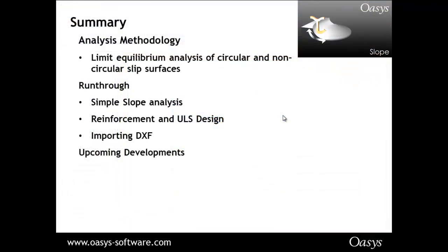So in summary, I've run through the analysis methodology. So now you should understand a little bit more about the limit equilibrium analysis of circular and non-circular slip surfaces. I've run through a simple slope analysis. I've also helped you look at how, for example, you would approach factor design in Slope, and then go on to design reinforcement. We've looked at, for example, putting raised groundwater tables in, putting loading on the slope. I've then introduced the importing DXF feature, which would really simplify, for example, complex geometry or lots of stratas. And I've also introduced you to a very exciting upcoming development, which we're hoping to release over the next 6 months.